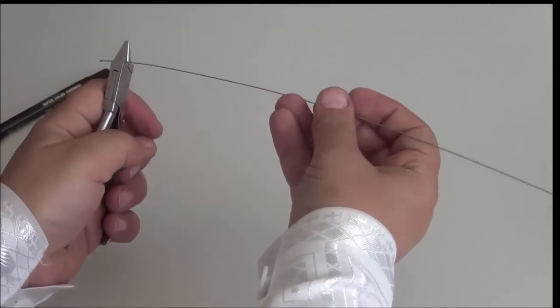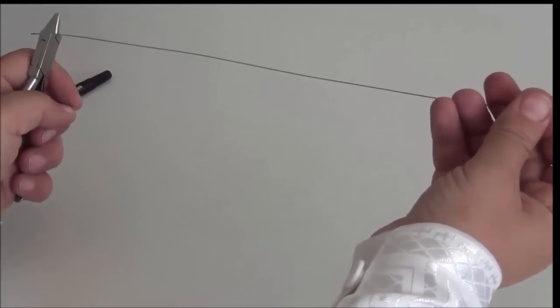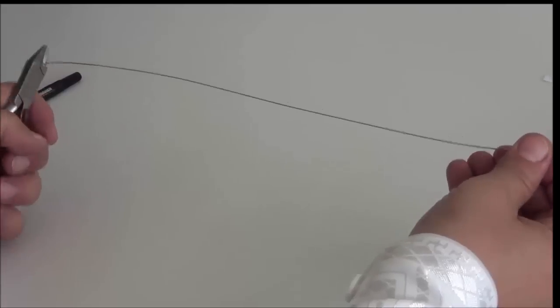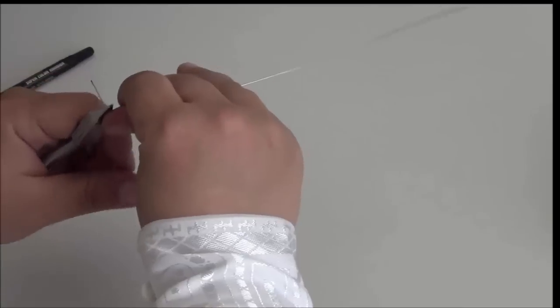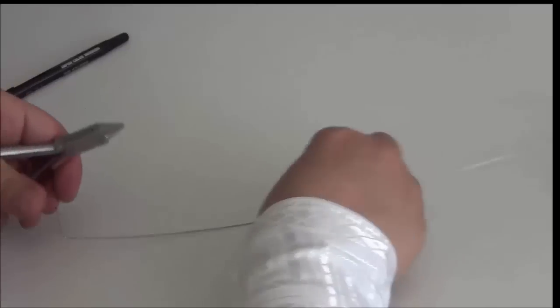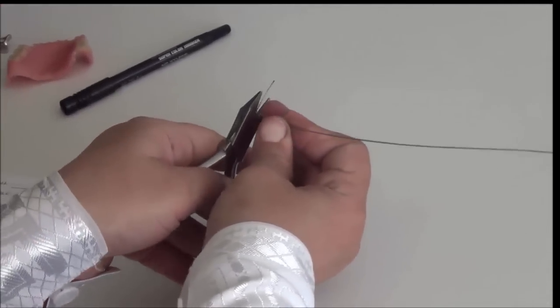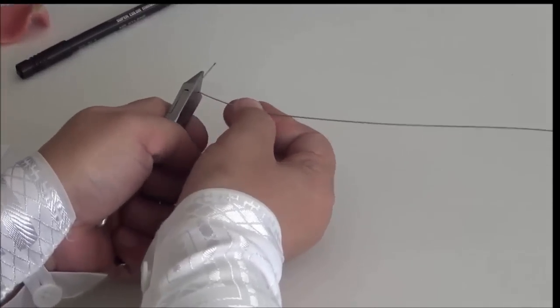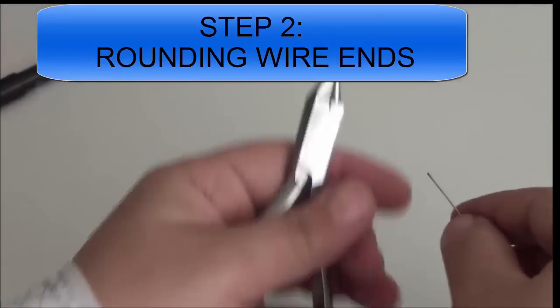Another skill that we need during the bending is having what we call a fixed point, because while I'm working, the wire keeps rotating. So it's good at the beginning to make sure that I have a point that I compare with to make sure that my wire is straight or not. So I keep comparing with one direction, okay, and this is my point of fixation, and I begin working towards it.